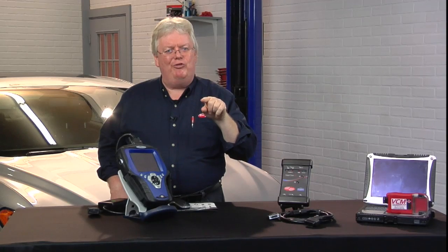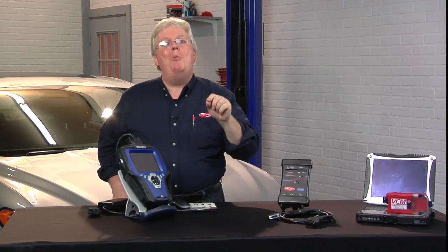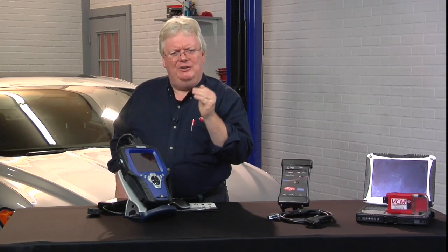Guess what happened? With fresh O2 sensors, you now have the catalytic converter efficiency monitor running, and it may run 2-3 times, be borderline, and then 2 weeks from now, it finally ran and it failed and turned the light on. It failed twice, turned the light on. How could you have prevented that comeback?